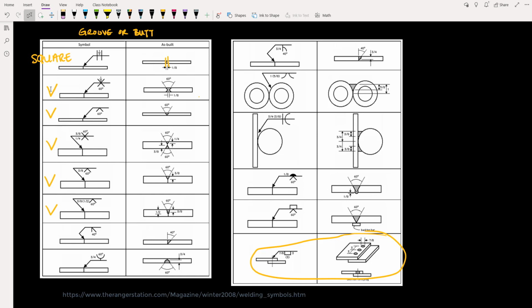When joining parallel elements, it's often actually preferred to use some type of V-weld, and there are several different configurations that are given here, or perhaps a bevel weld. Next we have the U weld, or a J weld, and after that we have flare welds. So we have flare V and flare bevel weld. These type of flare welds can often be pretty expensive. So you can imagine welding round to round is not very ideal, or even welding round to straight.